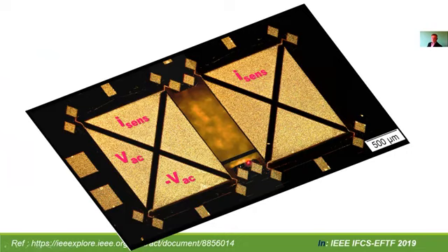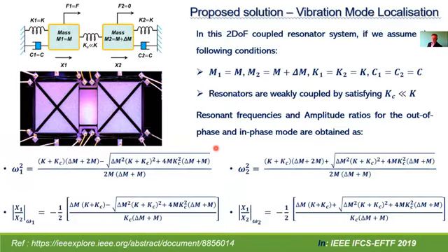This simple mechanical beam coupler connecting the two MEMS resonators makes all the difference, which works based on the vibration mode localization principle. In simple terms, we can model this coupled MEMS resonator system as a mass spring dashpot system.